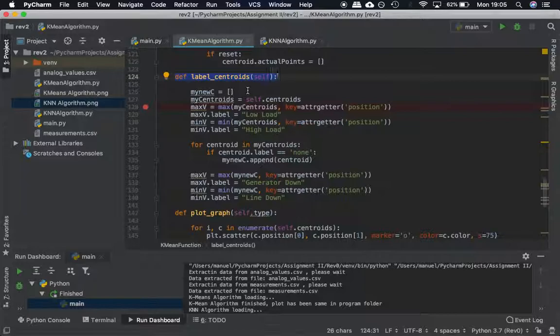The next label will be the one for the generator down. In our case, we have 9 buses. 3 of them are classified as slack bus or PV. When a generator is out of operation, which means shut down, in the connections between contiguous buses, theoretically they are at the same voltage levels, as well as the phase angle being the same, which means that there is no power flowing through that line.